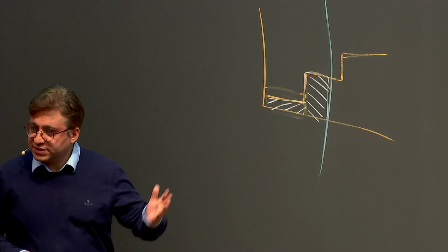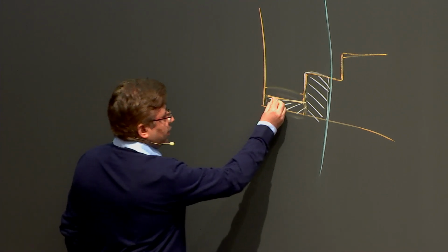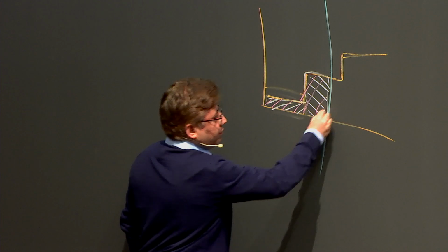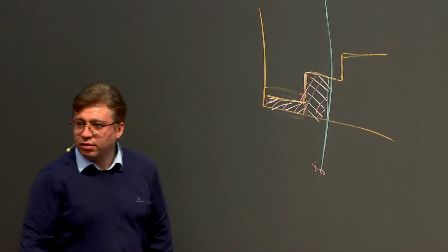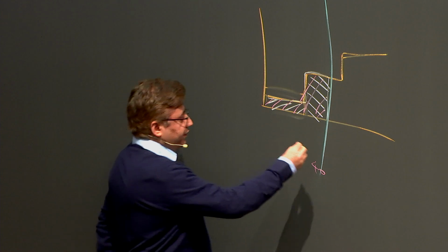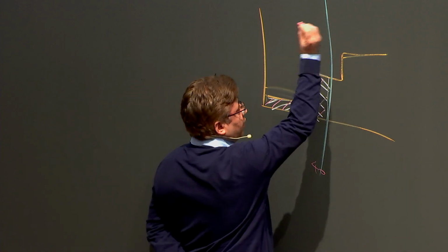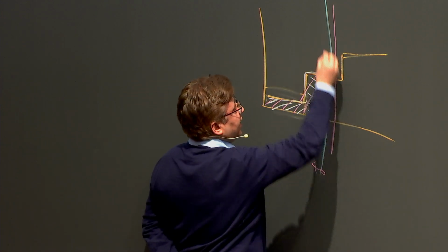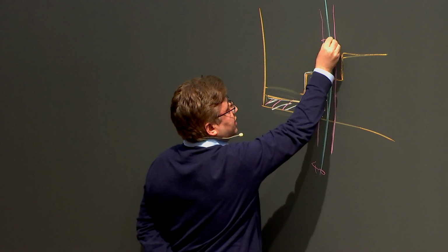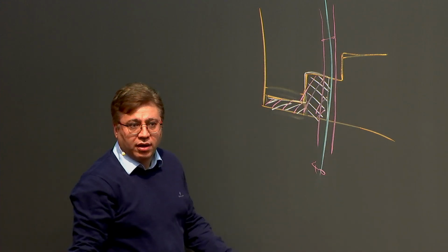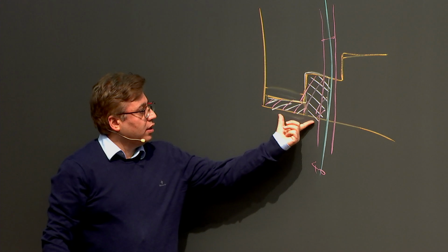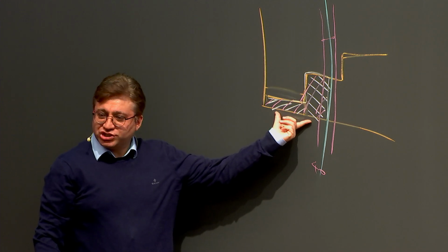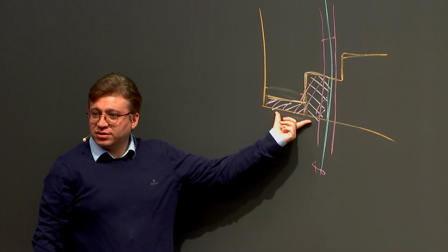Here in this case, the objective function is the total cost, which we said is this area. And demand is 40, right? If we change 40 to 40.1 or something like that, on either the right-hand side or left-hand side, by changing demand a bit, lambda shows how much the generation cost changes.